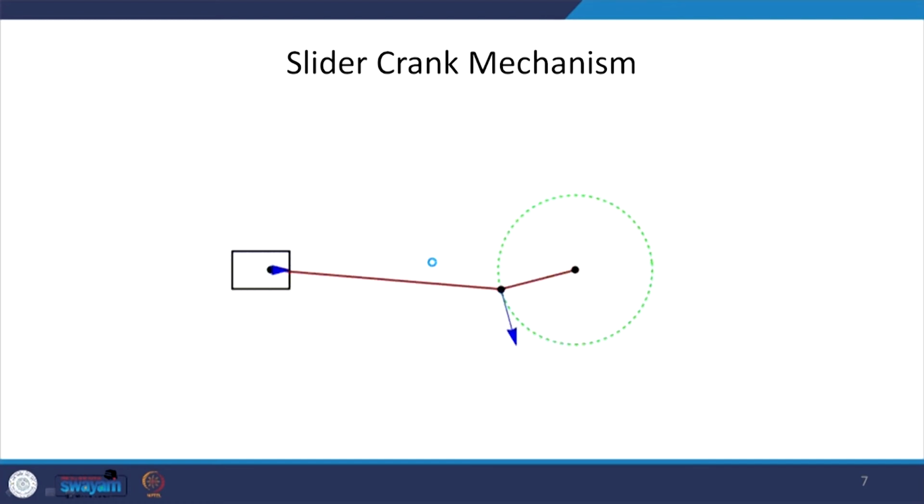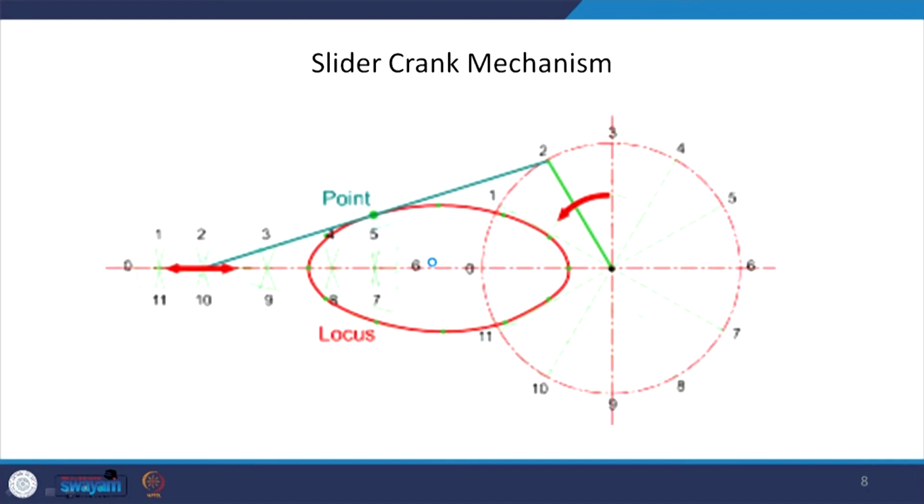Now, in this case, what is actually happening is that we have a crank, which is this green line, say OA, and we have a shaft or the slider, which is this line AB, which is exactly how the internal combustion engine or your sewing machine works. In very common sense, you must have seen a sewing machine. So, what happens? We move this crank. The handle of the machine is actually moving the crank of this machine, and this crank is connected to a shaft which moves.